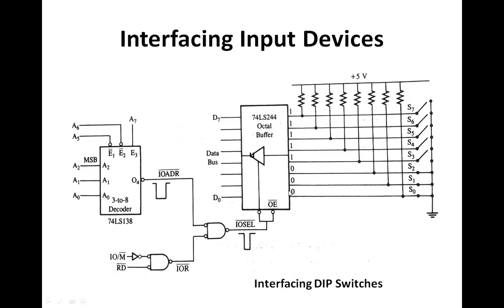Because 2 machine cycles will be elapsed in fetching the instruction, and then the purpose of using the IN instruction is to copy the data from the input device to the accumulator. So it will be using the 3rd machine cycle. And in this 3rd machine cycle, the control signal will be generated, that is the read signal. And the data will be flowing from the input device through the data bus to the accumulator or to the microprocessor.